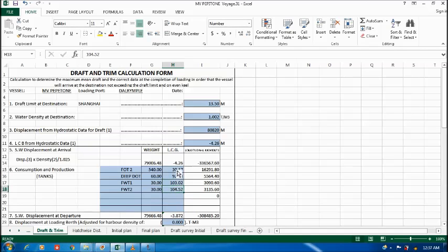Just go to your hydrostatic table of the vessel, and on the forward part of the page, in the vessel's specification, we have the tanks there: cargo hold, fuel oil tanks, and the ballast. You will get the LCG. You just copy it and put it right here. Also, you have to copy its sign value, either positive or negative. Just copy it here and put it.